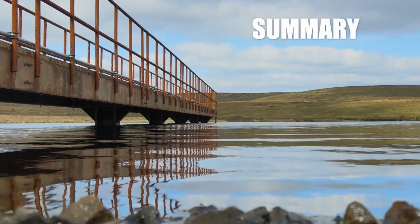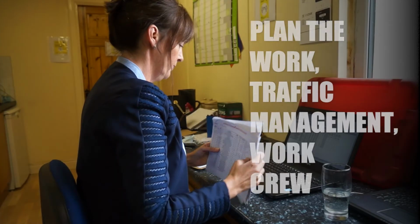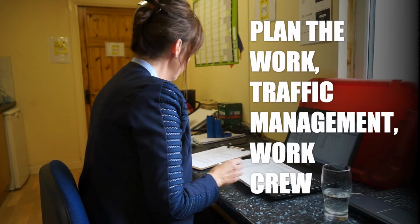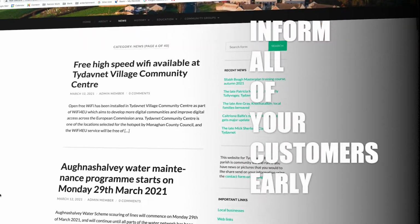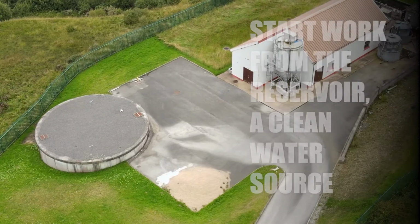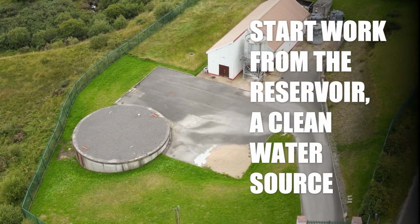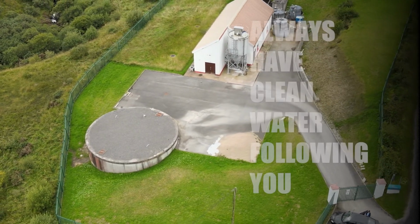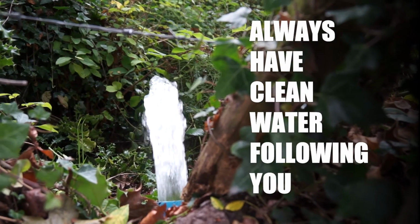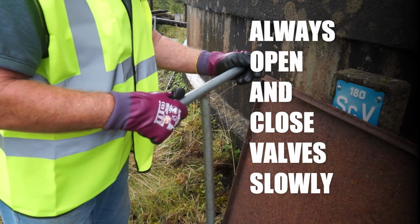Know your network, valves, pipe diameters, pipe materials and scours. Plan the work, traffic management, work crew. Inform your customers. Assemble and check equipment. Work from the plant or the reservoir out through the network, so that it works from a clean water source. Always have clean water following you. Open and close valves slowly.